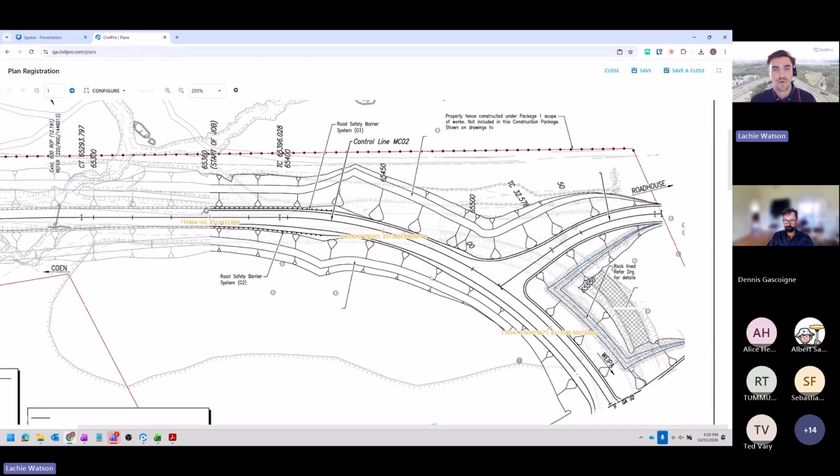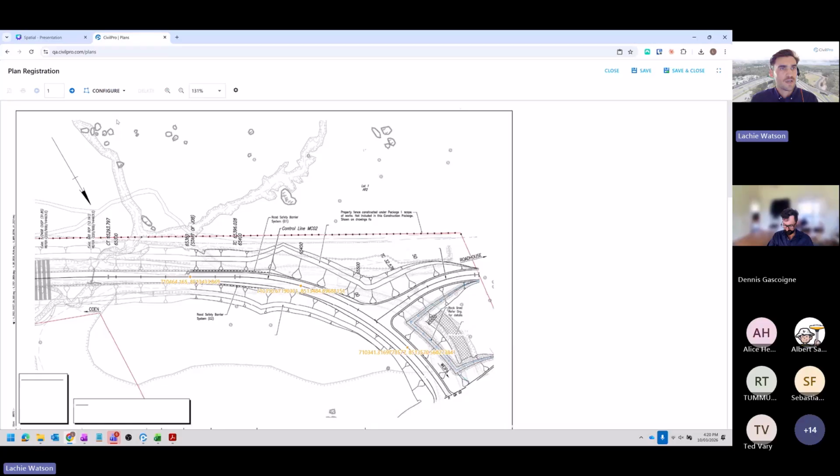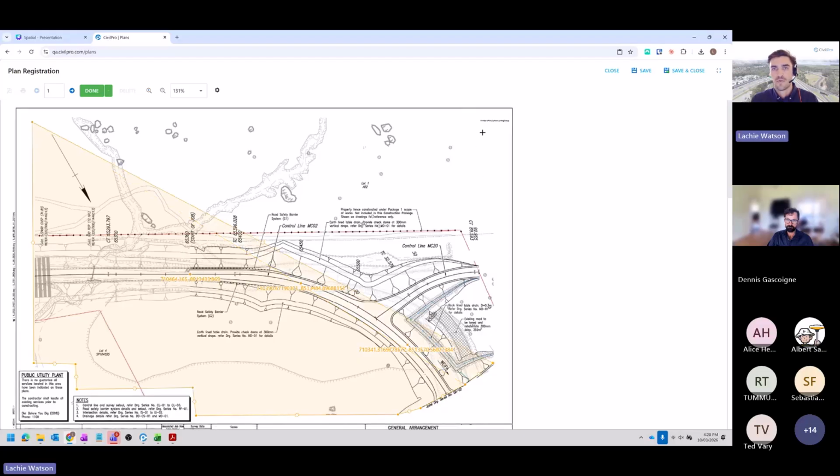Right, now that I have added those 3 points, the next thing I've got to do is define the perimeter that I want to have visible of this drawing. So I've just zoomed back out there, and I'm going to go into configure, add perimeter. I'm going to make this a little bit coarse for the interest of time, but you can always edit this afterwards. And what we want to do is run just along the join lines. Cool, that's slightly terrible, but that'll have to do.